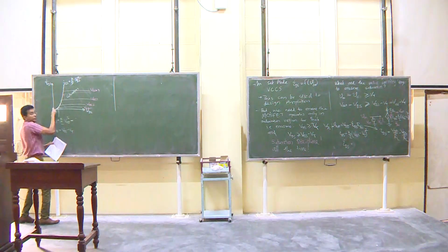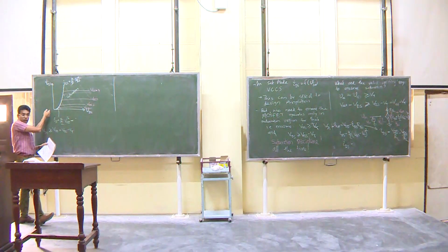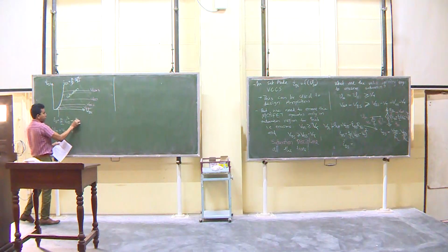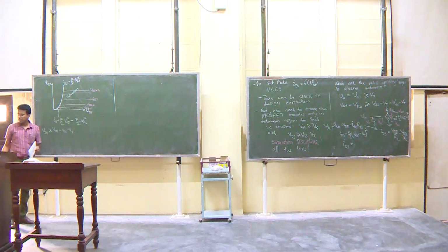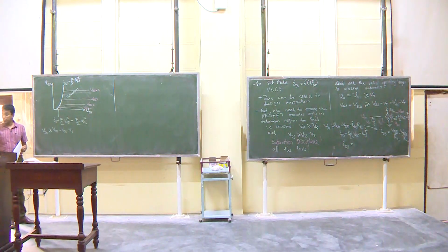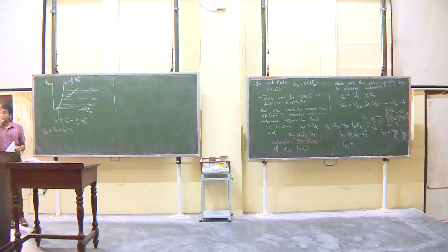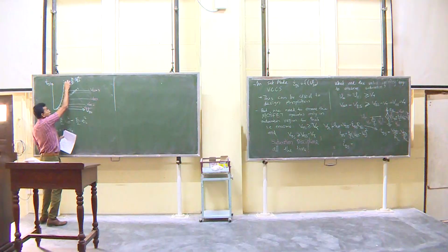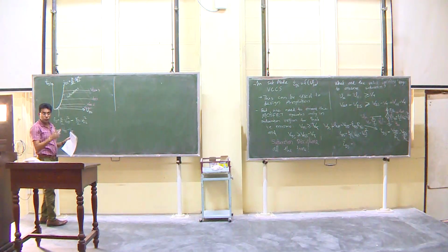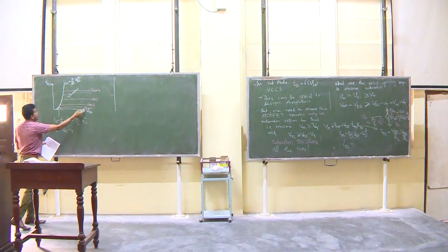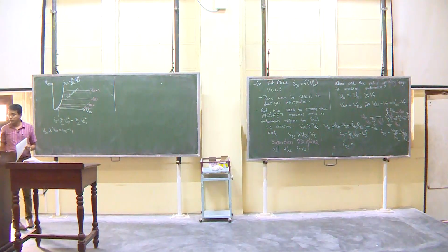On this graph, what you have is K divided by 2 VDS squared. Is it clear? Because remember earlier what you have, VGS minus VT, nothing to do with VDS. This is VDS, not VGS. Earlier the equation was IDS is equal to K divided by 2 VGS minus VT squared. Now here what we are representing is between this and that, right? Okay, hopefully that is clear.